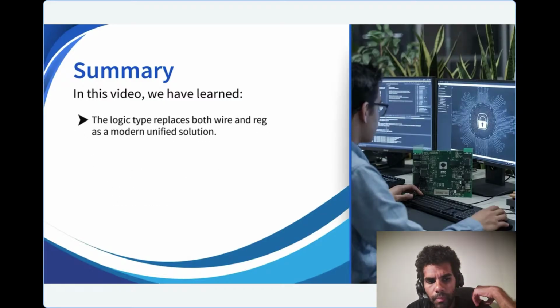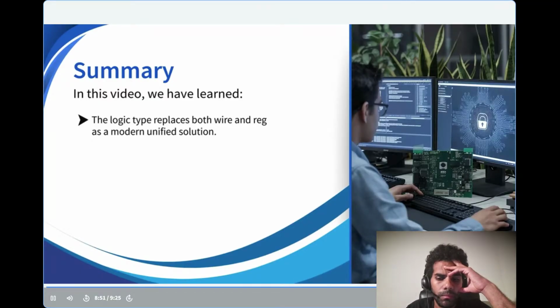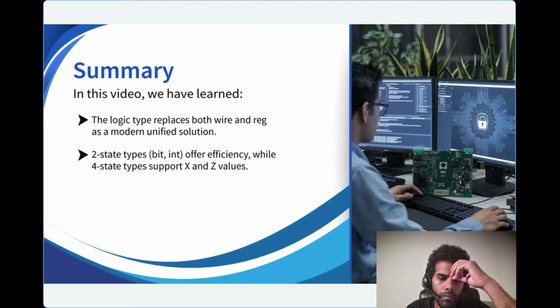The logic type serves as a modern unified replacement for both wire and reg, working in both procedural blocks and continuous assignments. Two-state types, bit and int, provide efficient representation when only 0 and 1 are needed, while four-state types support x and z values for simulation.